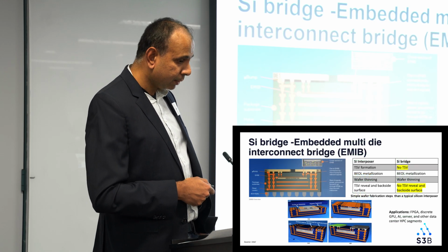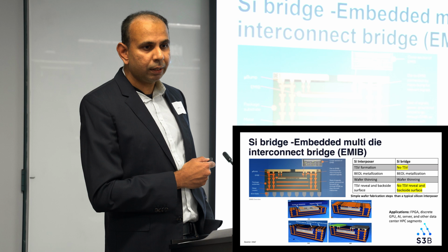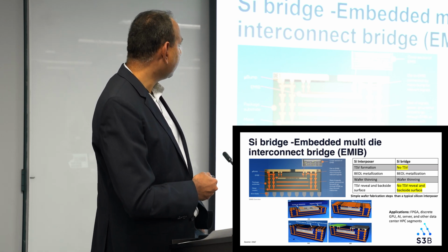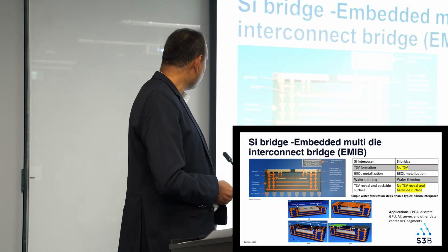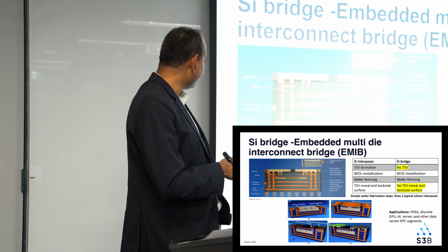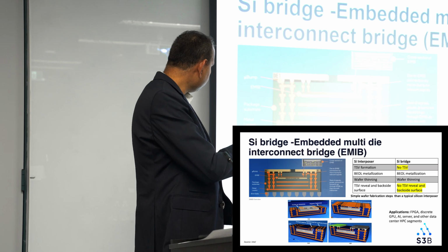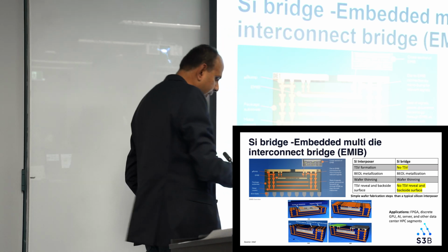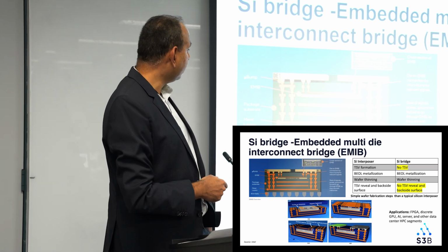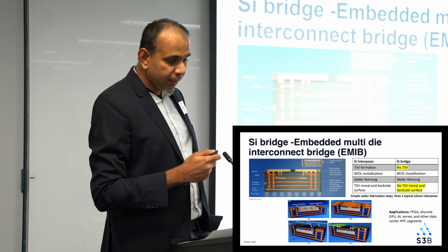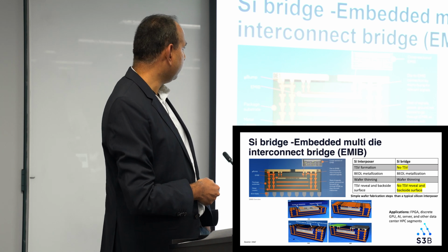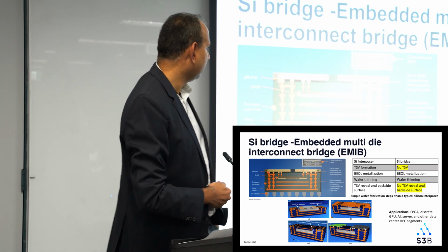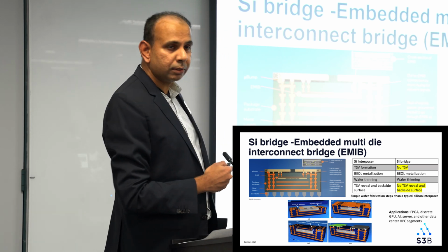Then moving on with the silicon bridge, as I mentioned earlier, for the 2.5D integration. Here I wanted to share the embedded multi-die interconnect bridge process from Intel. What they have done is embed a silicon bridge within an organic substrate. The advantage of using such a silicon bridge process instead of TSV is that you need not do all those through silicon via etching and other additional processes related to that.